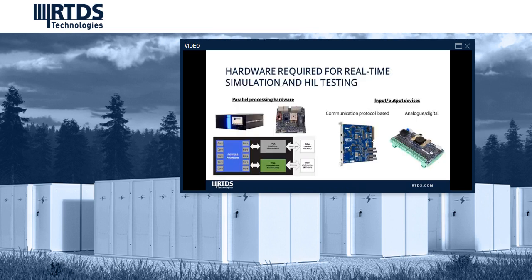To do nodal analysis on the power system with a 50 or 25 or 1 microsecond time step is very computationally intensive. And of course, the processing power required increases with the size and complexity of the network that you want to simulate. So to achieve this, the RTDS simulator is built on dedicated parallel processing hardware. Our current hardware generation is based on IBM's Power 8 multi-core processor, and we've developed it at the embedded level. So there's no underlying operating system.